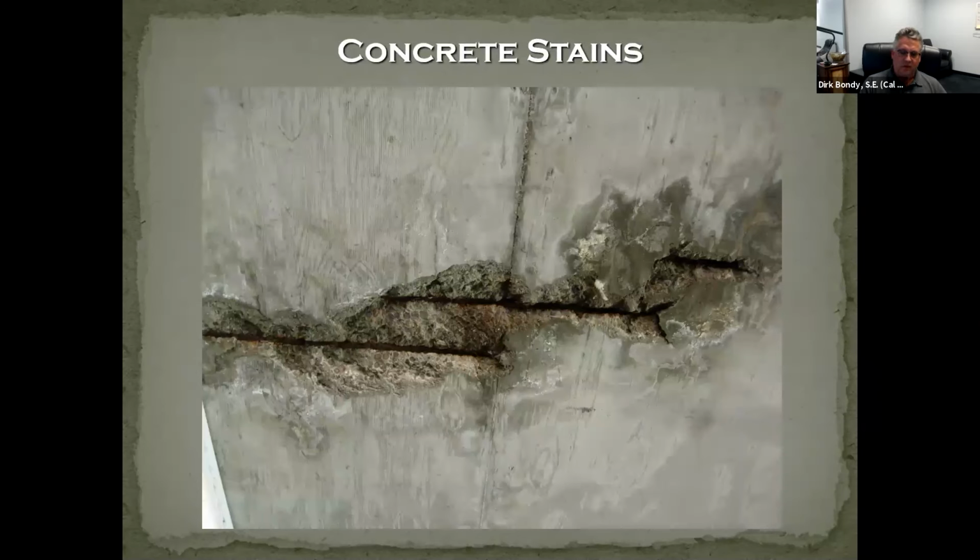A few years later, that will look like this. Now, this is just rebar. This isn't a post-tension structure, but it doesn't matter. We fix and repair and find the same corrosion problems in reinforced concrete. By the way, that Surfside condominium project in Florida that collapsed, that I think everybody in the world knows about, was just a reinforced concrete slab. It was not post-tension. But I don't know what happened there, but we're seeing reports that they had damage that looked like this.